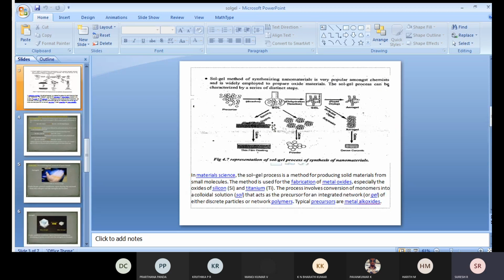The fifth important step is the calcine, or calcination; both are the same thing. It is the final step, in order to get the raw materials of the nanoparticles. Once the calcination has been done for the spinning process, we get the thin film coating. If you do the calcination for the Sol itself, you get the powder particles. If you do the surfactant organic process, after calcination we get the dense ceramic.